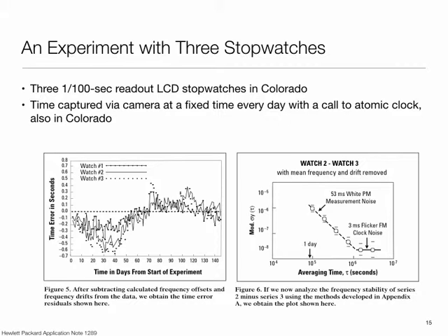Now, that can be somewhat risky because when you look at a clock data sheet, there are a couple of key numbers that one has to worry about. One number is the maximum error from the nominal that the manufacturer states. That depends upon the quality of manufacturing. These are crystals, they cut the crystals, so the error in cutting the crystal translates into an error offset in the frequency, and that's expressed in ppm.